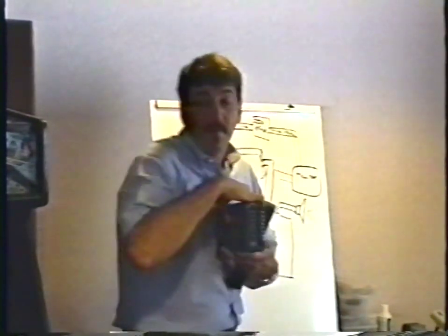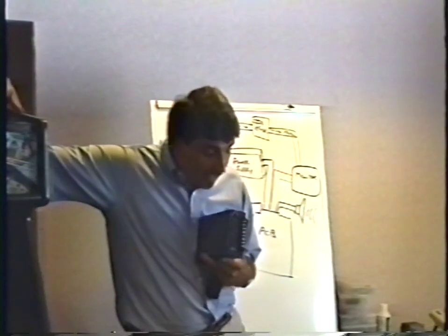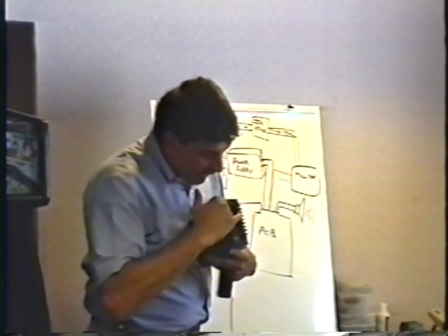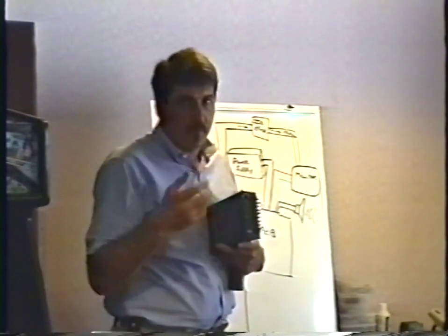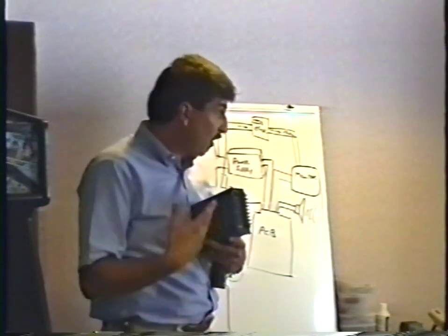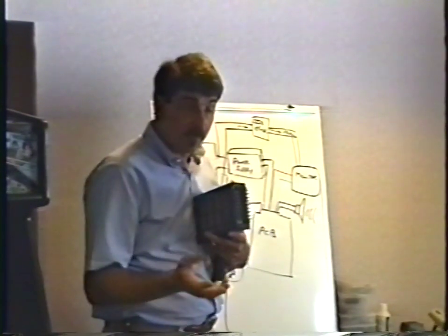so you get to the game and you coin it up, it doesn't do anything. You've got to assume your power supply is crapped out. And the easiest thing to do is you put your meter lead on ground, the black meter lead on ground, the red meter lead on plus 5, and with the game turned on and powered up, you should read 5 volts DC there. If you don't have your 5 volts DC there, there's nothing coming out of the power supply.